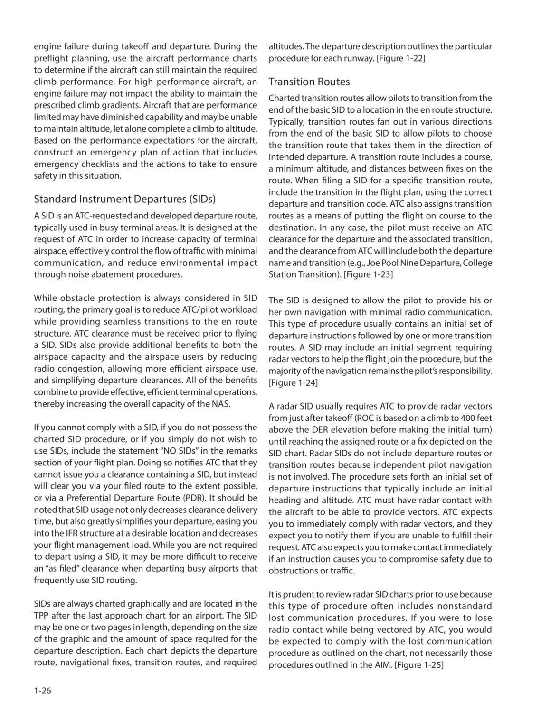It should be noted that SID usage not only decreases clearance delivery time, but also greatly simplifies your departure, easing you into the IFR structure at a desirable location and decreases your flight management load. While you are not required to depart using a SID, it may be more difficult to receive an as-filed clearance when departing busy airports that frequently use SID routing.